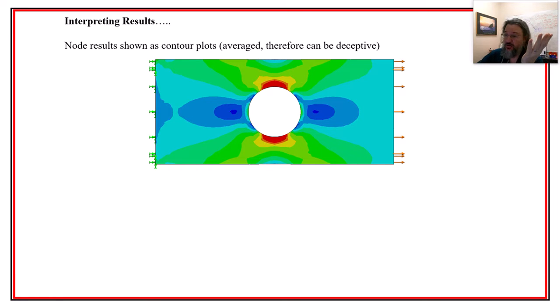That's the same thing here. You can learn how to run the machine, and we could just give it to anybody. You don't need a mechanical engineering degree to run FEA. Anybody can do it. Anybody can learn to do it. But if you do the thing wrong, if you don't know what's going on, if you pick the wrong boundary conditions and so forth, or if you don't have some idea of the limitations, you could have very wrong results.